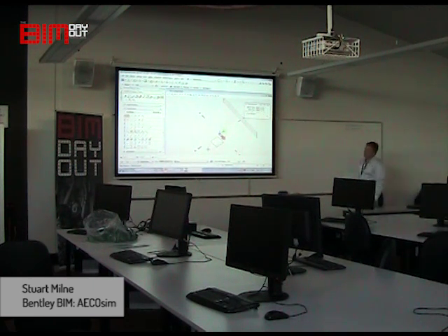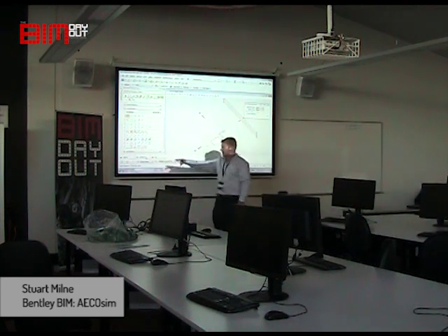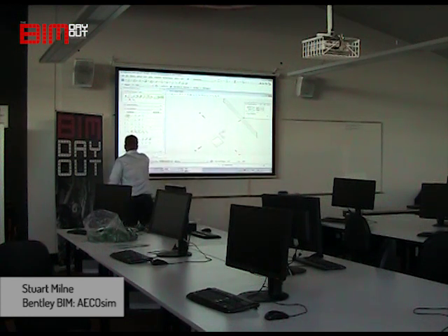Okay, so what we've actually done there, we've actually used 2 AccuDraw keyins so far. Well, 3 effectively. We used top to rotate the AccuDraw compass to the top. We used enter to make it stick to the axis. And we entered in some values. Now, when we did all that was in this box down the bottom here. Every time we did something through there, we have this box that says X, Y, and Z. And we did all that through that box there.